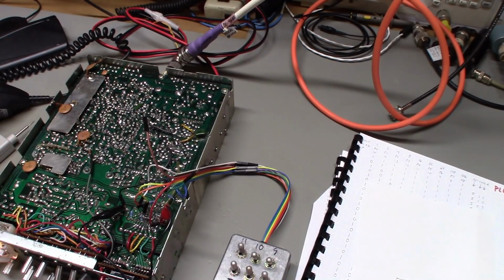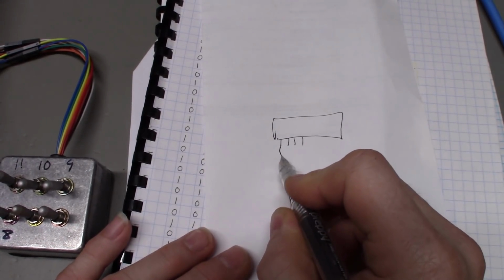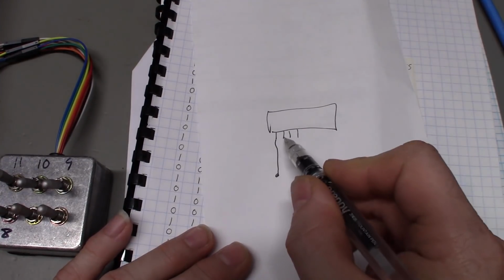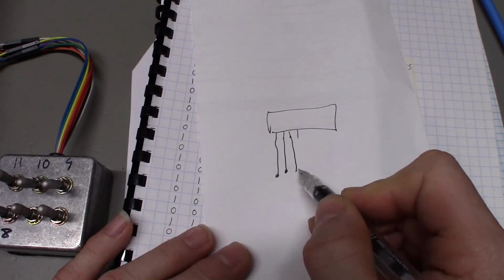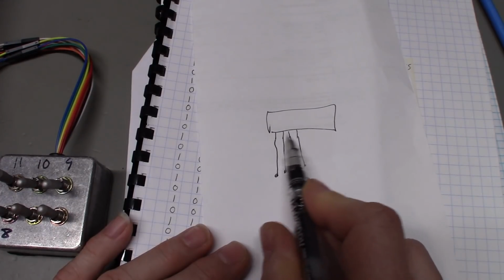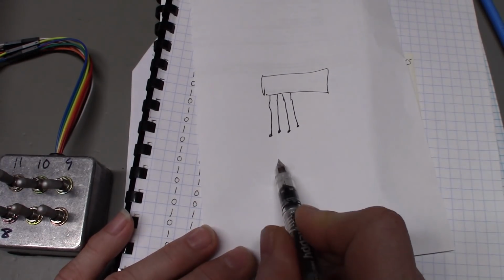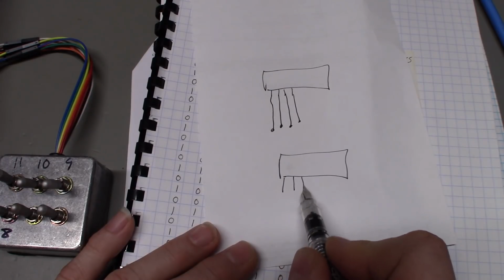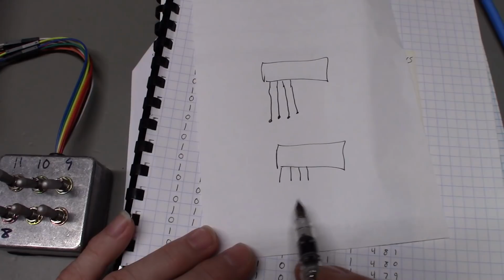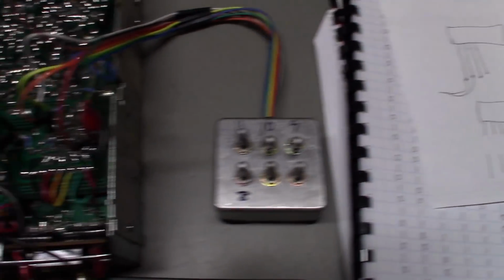Okay, so let's say here's our IC, and we've got a couple pins on the IC, and they're attached to circuit traces. Those circuit traces, like in the case of that radio over there, just come out to pads where those wires are soldered. Now, let's say these 4 pins were pins that you needed to change the programming states on. After you got done modifying it, you'd have your IC with 4 traces coming out, and they'd be cut. Remember, this end goes off to the channel selector through these wires, down to the channel selector board.